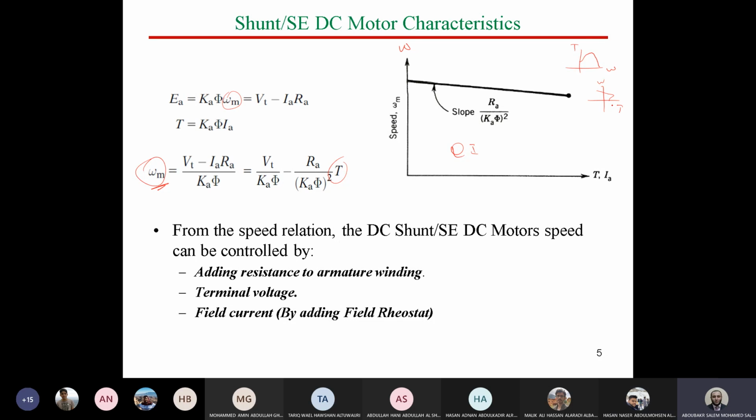However, I just refer to one important thing. If you say quadrant 1, quadrant 2, quadrant 3, you have to respect the standard orientation, which is omega on the vertical axis and torque on the horizontal axis. If you say that this is number 1, you cannot say this is number 2. This is now wrong, because this one is considered number 4.